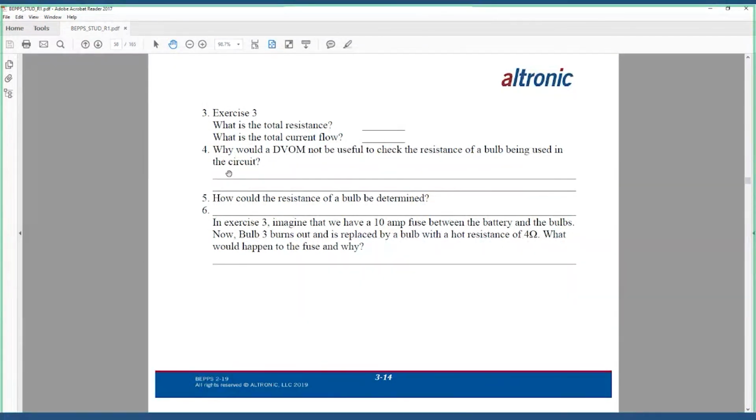But that concludes this section. A little bit topsy-turvy to some degree here and there with what we were doing today. But hopefully what we've learned is parallel circuits. We've used Ohm's law a little bit in the exercises, and on a series circuit we can total the resistance in them. In the parallel circuit, if we know the resistance values on each leg and how many legs are in the circuit, we can divide as long as the resistance is the same.